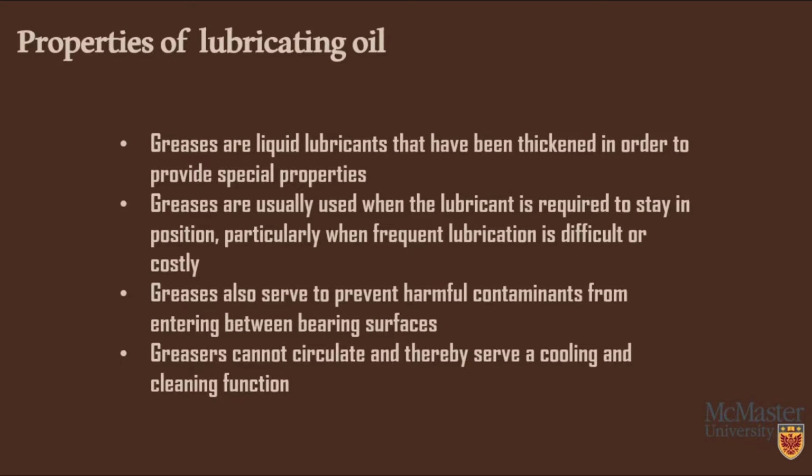Grease is a liquid lubricant that has been thickened to provide special properties. When lubricating, oil is required to be kept in a proper position. Lubricating grease is usually used, especially when frequent lubrication is difficult or costly. At the same time, grease can also prevent harmful pollutants from entering between bearing surfaces. It should be noted that grease cannot circulate, so it has no cooling and cleaning functions.